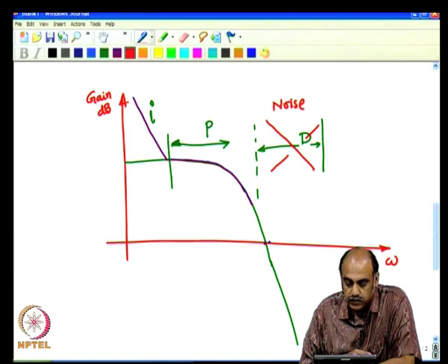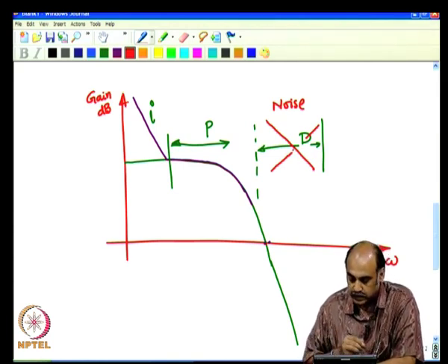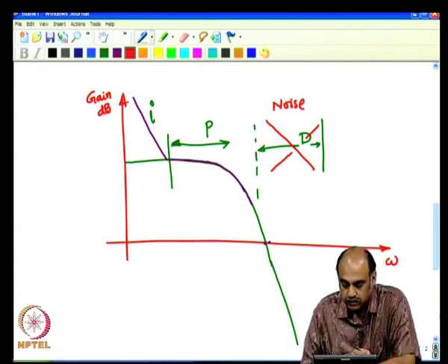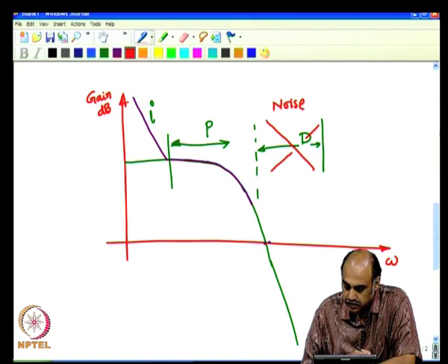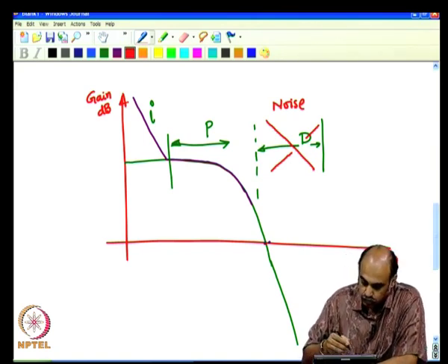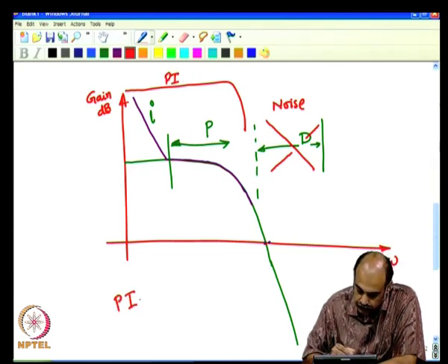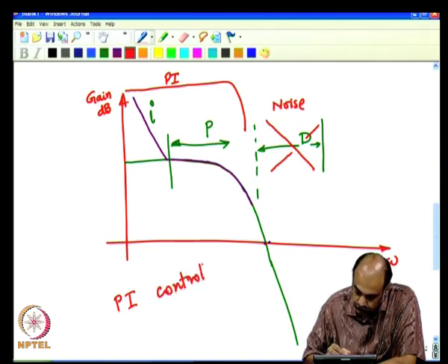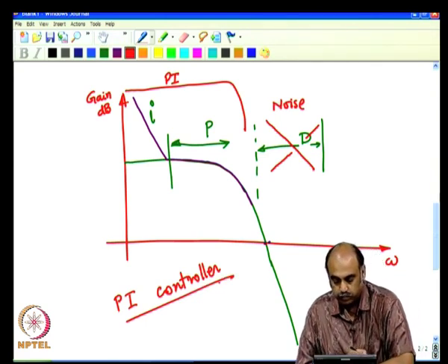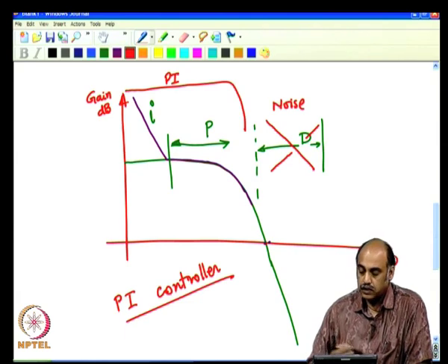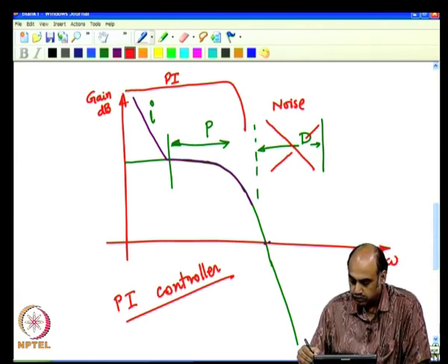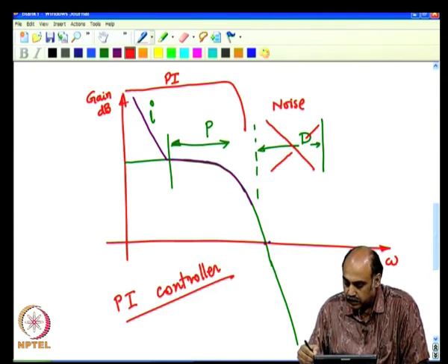If your system works well with just P and I, then stop with it, do not go further to include the D. Only when your dynamics are not really up to the mark and you really want to improve the dynamics, you try to put in the D. Most of the controllers will just have the P and the I part, and therefore, you have what is called the PI controllers. The PI controllers are the ones which are most popular, and most of the plants seem to be okay with just a PI controller. They suffice and meet the specifications. Include the D part only if absolutely necessary.